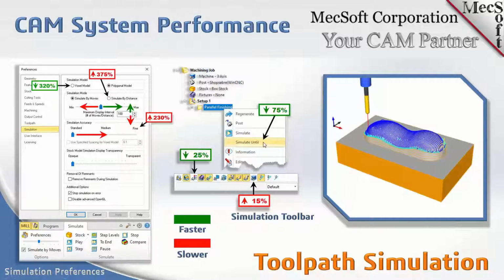For many 2-axis and many 3-axis, and Joe, you can jump in and tell me which ones don't apply, but many you can run in a voxel model simulation, and you can drop that simulation time by over 300% in our tests just by using the voxel model. Now, it's going to be a less accurate representation, but if you understand your model and how it's going to work, you can use that to get a quick view of what the toolpath looks like.